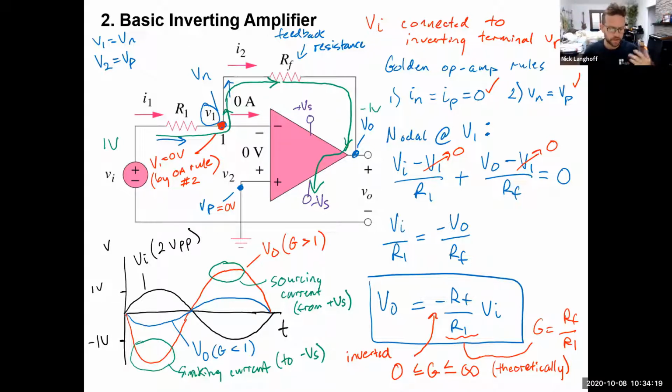To design those things, you actually have to make adjustments, often in the input stage and the output stage. But in doing so, if you make it really high speed, whatever you're adjusting there is going to make it work less well for other applications, like low power, for example. So the higher speed the op-amp is designed to be, the less of a low power op-amp it is, one that doesn't consume much standby power when it's not running and doing its job. Those are the kinds of things that can make amplifiers expensive.